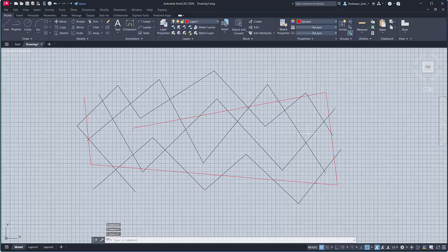So let's take a look at some of these other menu items and what we can do. So right now, all that we've done is we've drawn a couple of lines. And again, ignore the layers command. We have a formal lesson in that. But I want to change this. I want to modify it. I want to erase it. So when I erase, I'm changing something that's already there, and therefore I've already used the terminology. I'm modifying it, and therefore I go right into the modify menu. There it is. And in here, I'm wanting to erase some lines.